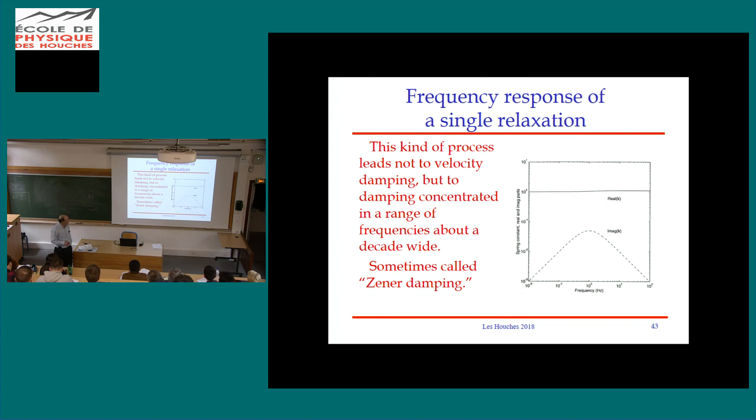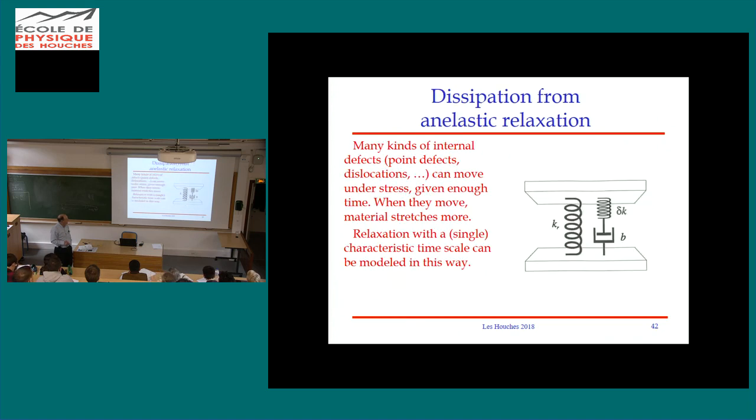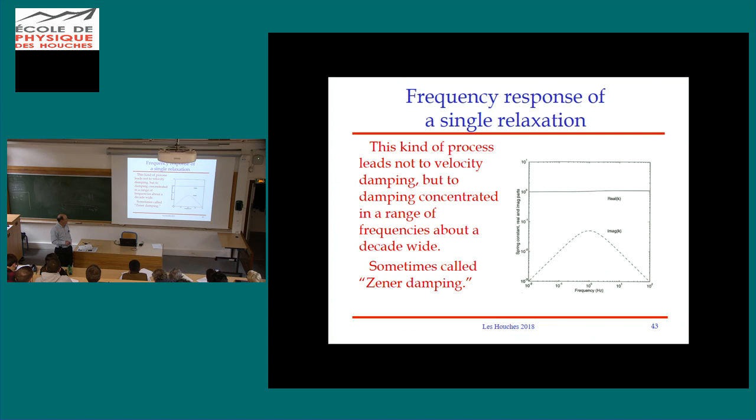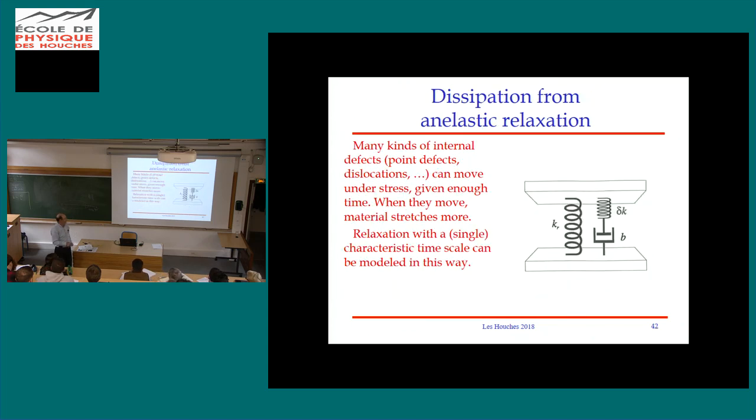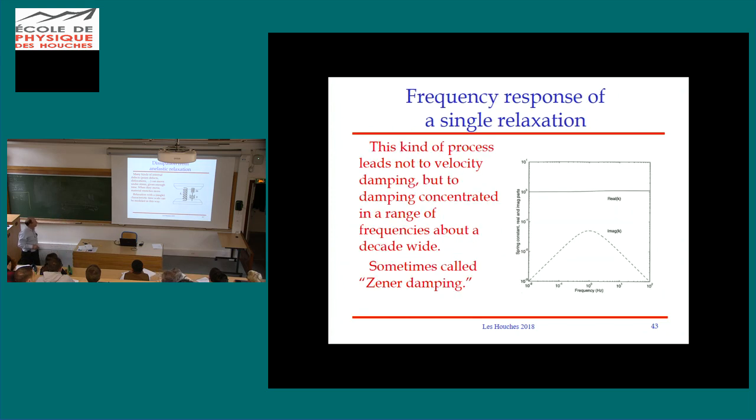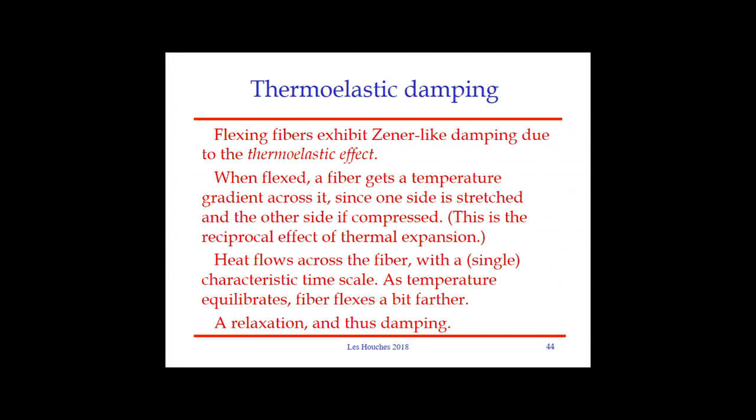Note, this is an interesting side effect, that it has to be the case that the low frequency stiffness and the high frequency stiffness of materials are different from one another. Because at high frequencies, you're stretching both springs. At low frequencies, you're only stretching the ideal spring. This is a mechanical example of the Kramers-Kronig relation, if you want to think of it that way. Now, it gets worse. Well, okay.